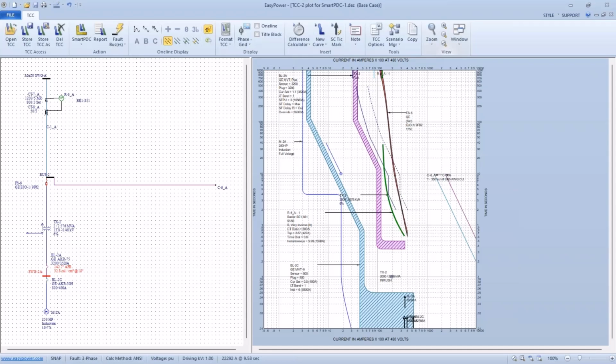So if I left click and drag on the fuse, the tool says, yeah, there's a 125 amp available in the device library that would improve the protection of the transformer, but it would also necessitate some adjustment on our relay function, all of which is good advice and should be considered as far as the discussion with the client.